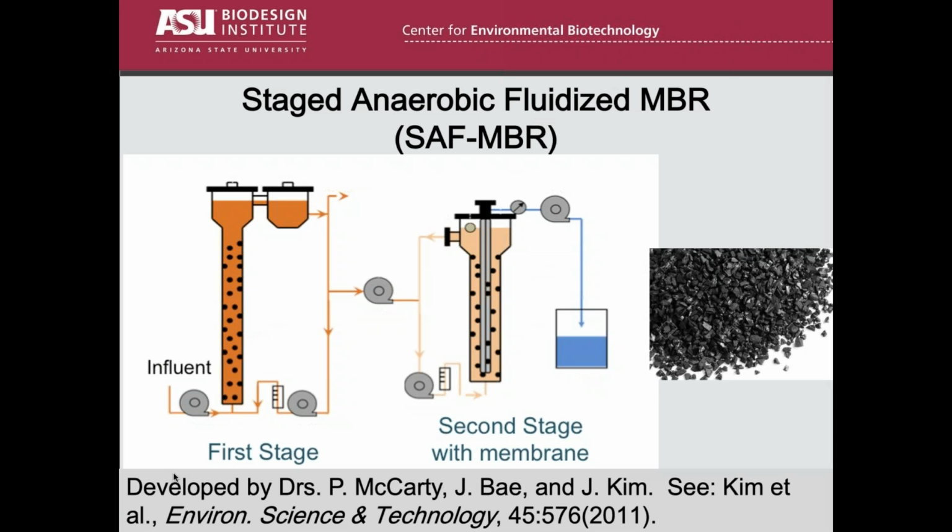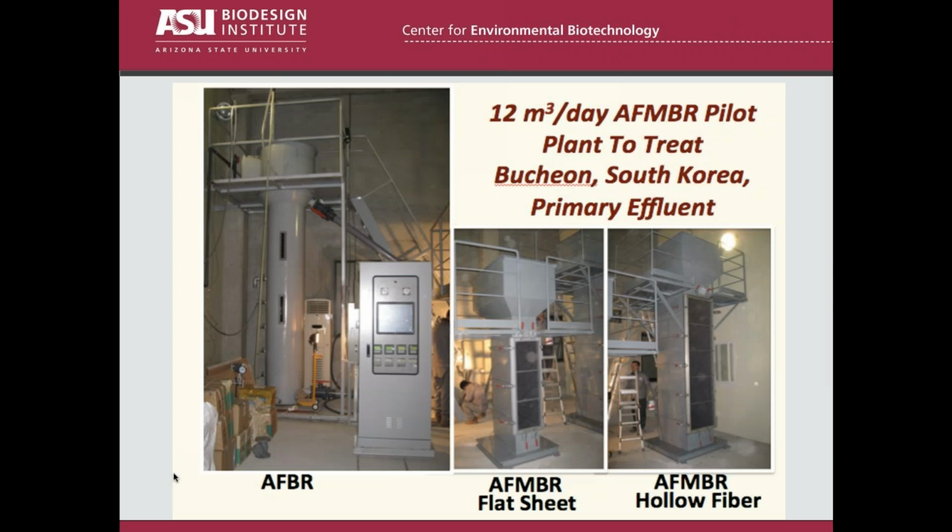And then the effluent from the first stage goes to the second stage, which also is a GAC-based fluidized bed, but you can see inside it, it has the membranes. And of course, they have to be inside the reactor because you're going to use the natural cleaning mechanism of the GAC bumping against the membranes to minimize the biofouling on this. So this has been tested extensively in Korea, Singapore, United States. And we've got a lot of data on it.